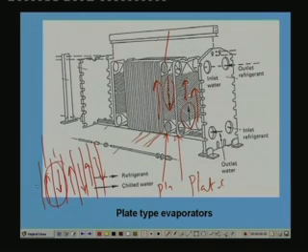So as we know, the counterflow gives rise to very effective heat transfer. And you can also see that these plates are not plain plates, but they have some profile on them. Normally they have some structure in such a way that good turbulence and hence high heat transfer coefficients can be obtained. Normally a herringbone structure or something like that is used. So the plain plates are taken and they are stamped with the required structure so that you get a high heat transfer coefficient.